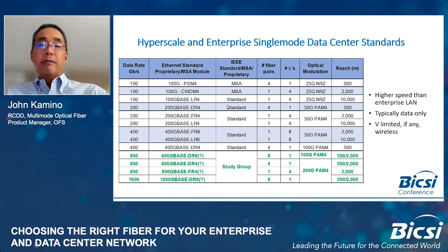That was really in response to hyperscale customers who wanted to go 500 meters, but didn't want to pay the price for a 10-kilometer transceiver. They wanted something that would go shorter distances and didn't have the robustness that was needed to go 10 kilometers. These are both MSAs that were developed in response to those requests. You'll notice that there's a standard LR4